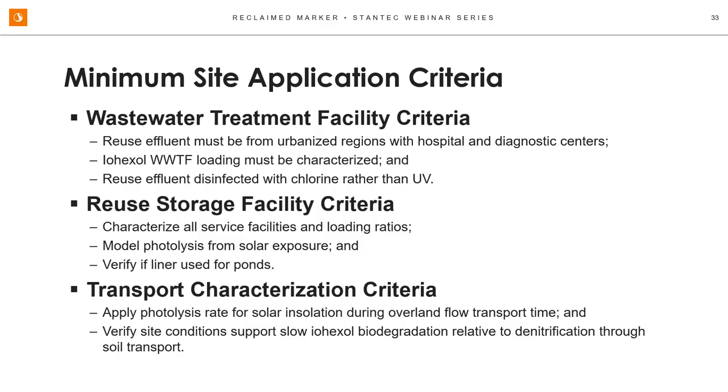So, sometimes you may have 2 or 3 different wastewater facilities that are all putting their reuse water into the same pond. That obviously is a complicating factor. And then you have to verify, is there a liner used for the ponds? Is the pond itself an actual infiltration point for the effluent that could be impacting the receiving water of concern?